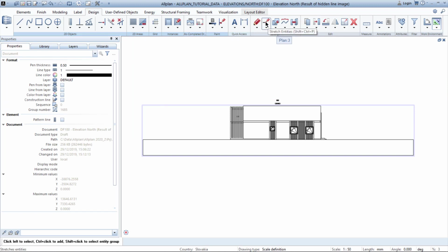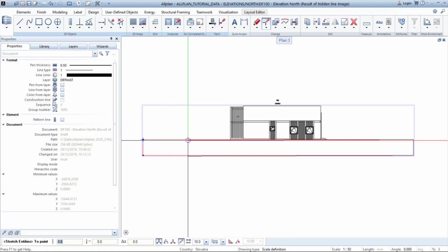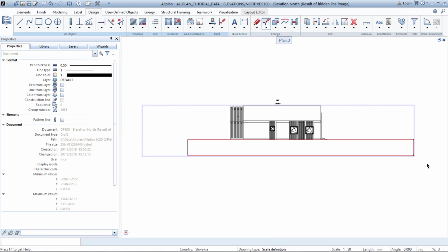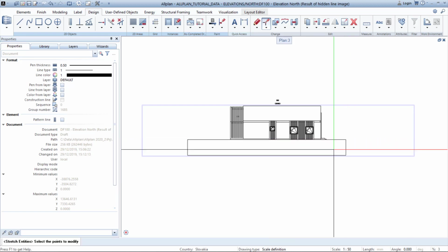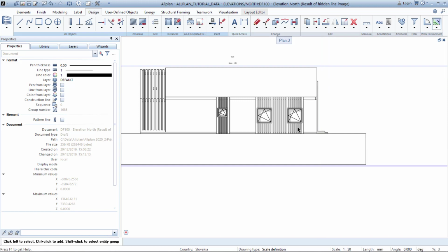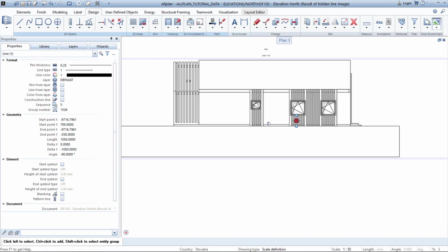Now I can use a function called Stretch Entities and shrink the ground depending on how I want it. What's important is that when you check Update Automatically again, all the changes will revert to the former elevation. You can also change, edit, or delete every single line individually.